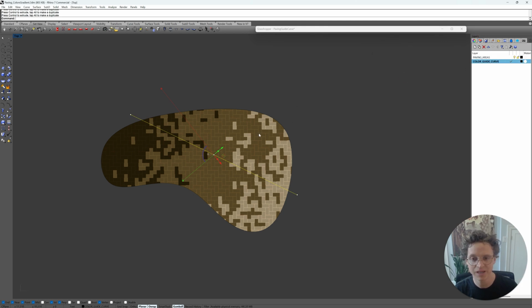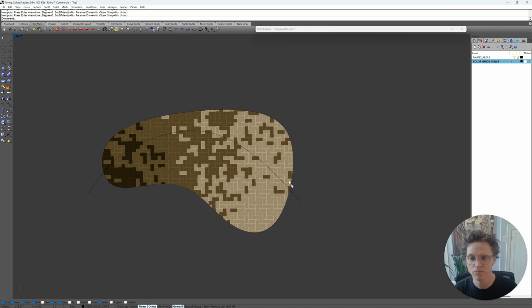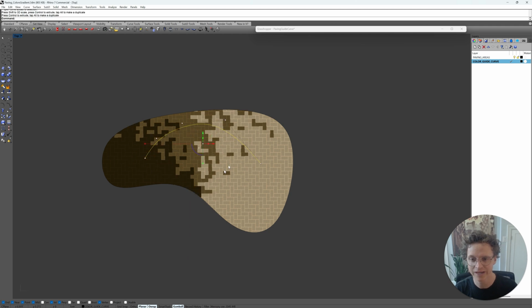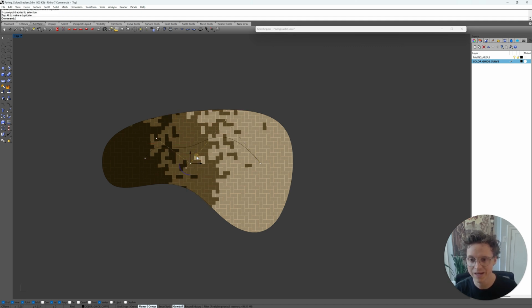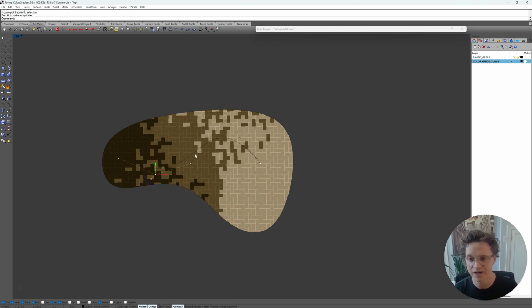Now, this curve can also be other shapes, such as an arc or a NURBS curve of sorts, to create a gradient that moves along the directionality from endpoint to endpoint of this particular curve. And you can see how that reflects in the gradient to create a triangular-like shape as it meets. As the perpendicular cutoff points for these colors meet each other, we have a meeting of the first swatch and the last swatch. So being able to create very unique and unusual gradient patterns across a paving area can be done using a variety of different curve shapes.